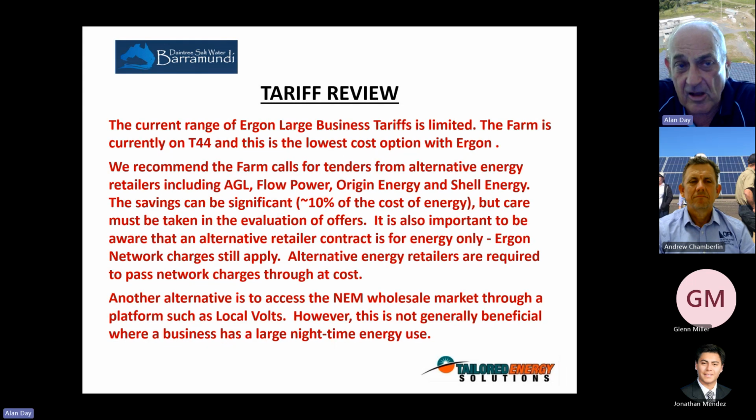So just in terms of the tariff review, they're on T44. Basically, Ergon, with the removal of agricultural tariffs, have limited their options. There are no time of use tariffs that make any kind of sense for this farm. It's 24/7, so the load's pretty level through the period. So there's nothing you can really achieve looking at time of use.